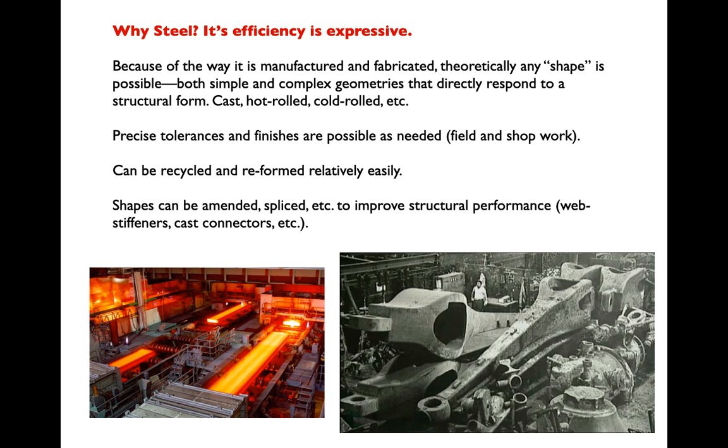In concrete, of course, we don't get this. The formwork has to be placed. It can move around a little bit. We generally don't expect concrete to be placed with any tighter tolerance than maybe 1/2 inch on the job site. Steel is much more precise, and therefore we can get much more carefully tuned shapes out of it, both in the shop and on the construction site.